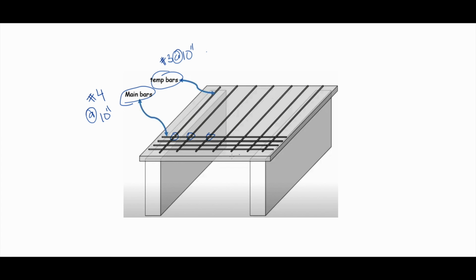You can see the main reinforcement, which is this one, is along the short direction, because once the slab is loaded, the slab will bend like that. This is the bending way. So we need the main reinforcement to be like that. And the shrinkage, why do we need the shrinkage?